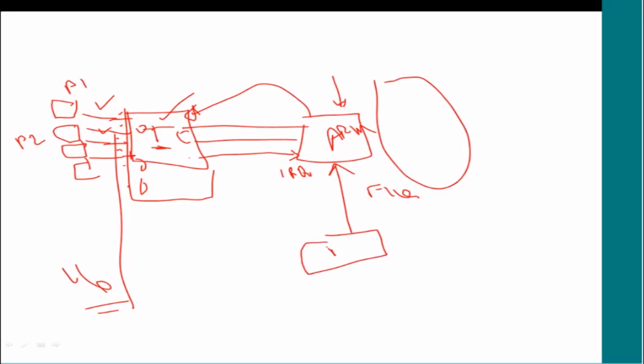The most important one, I should not put P1 here, it is P0. This peripheral is so important, so critical, that if it generates an interrupt, it should be serviced immediately. So you connect it directly to that. Whereas IRQ you use for connecting multiple devices to the interrupt pin. Now you may wonder, IRQ comes and then it goes to the vector table, right? And then it looks at the handler.